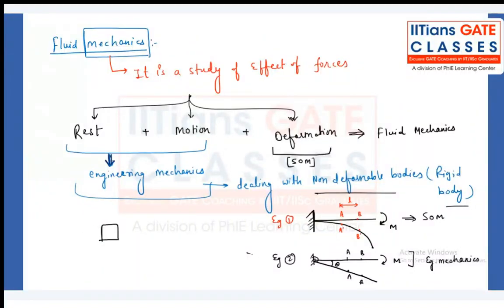See, you take a fluid body and apply a force, however very, very small. Think of it as a fluid. What will happen? It will continuously deform, and that deformation is what causes the fluid flow to begin. That's how we say the fluid is flowing. That means the fluid is continuously deforming. Suppose you are not applying any shear force, then the fluid is under what? Rest condition, right? The fluid is under rest conditions. It cannot resist shear force. Very good.